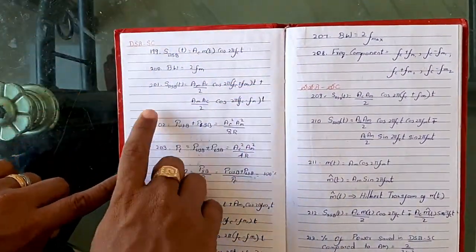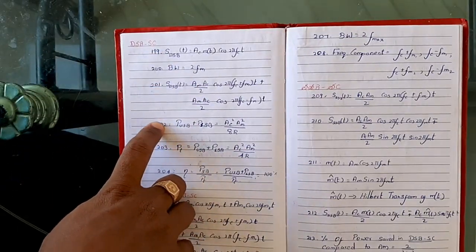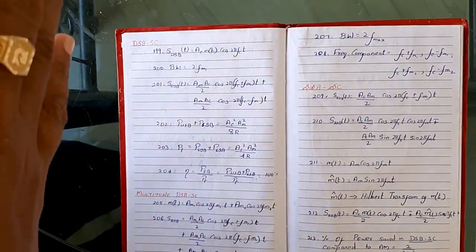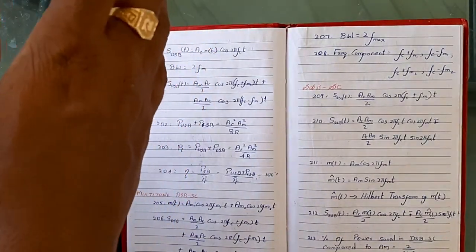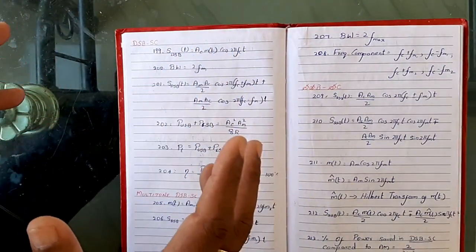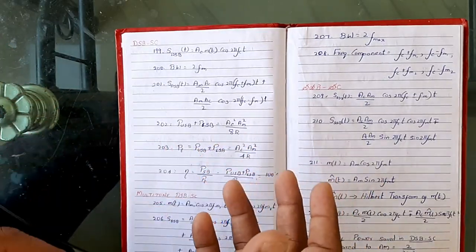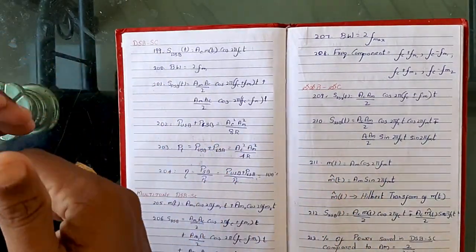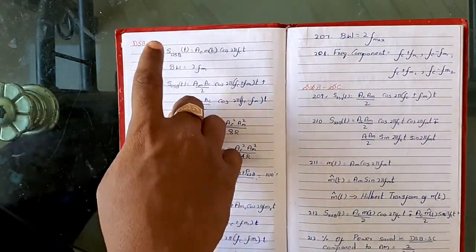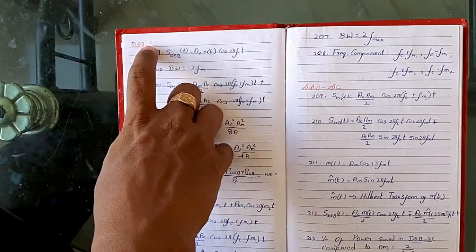The double sideband suppressed carrier signal. Double sideband suppressed carrier means this amplitude modulated signal will have the upper sideband signal and the lower sideband signal, whereas the carrier signal is suppressed. Since the carrier signal doesn't carry much information and is redundant while detecting the signal at the receiver end, it has to be suppressed to improve the efficiency of the entire amplitude modulation system. That technique is called double sideband suppressed carrier. Double sideband will be present, carrier will be suppressed.